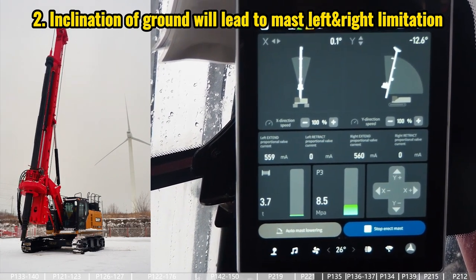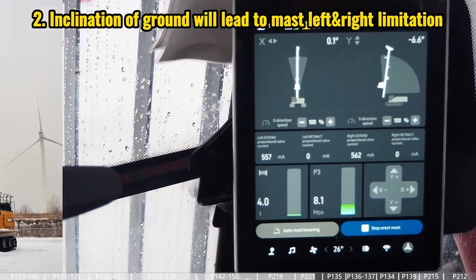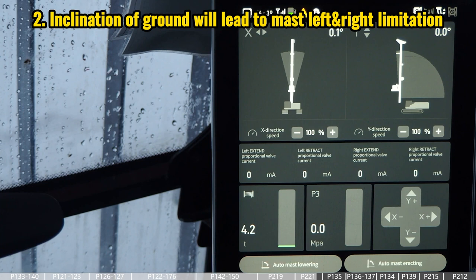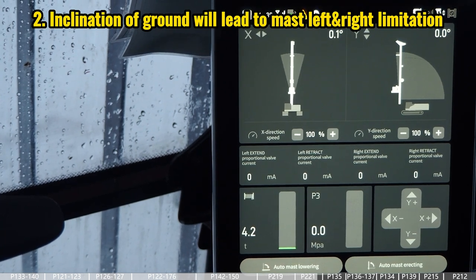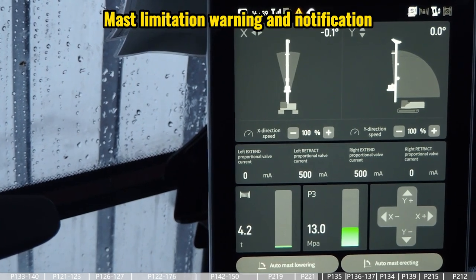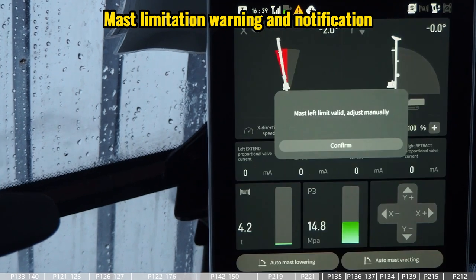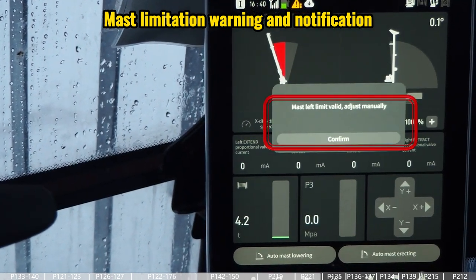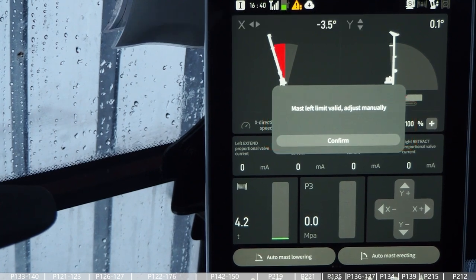If there's a big inclination between the ground and the horizontal, the mast movement is going to reach the left or right limit very early. And in the mast page, there will be a red highlight for the limited side, and also a notification is going to jump out, and we need to click confirm to continue the movement for the mast.